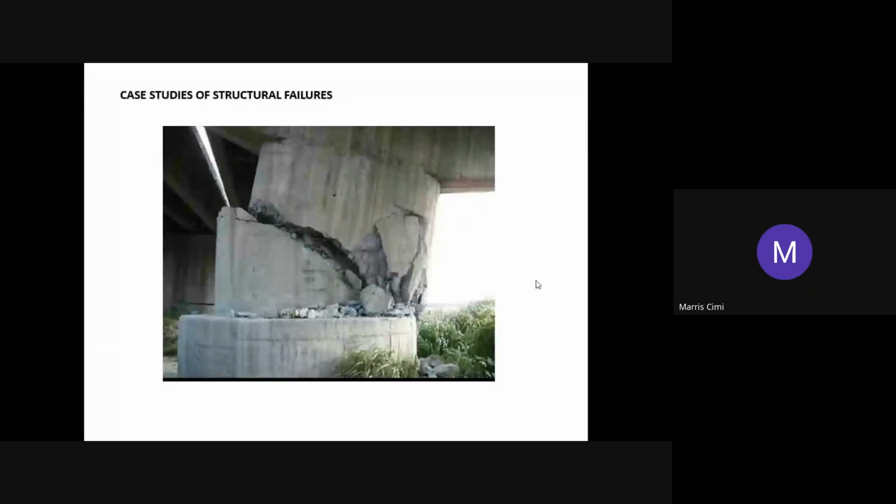Maybe the stirrups used for the reinforcement are not adequate, or not up to the designed material for that. The remedy for this is to take out this section, because it looks like a bridge, like you said, take out that portion, demolish this particular column and start it afresh.